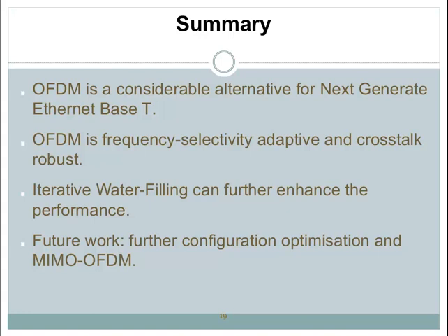And in the future, we will still focus on the possibility of OFDM with better configuration to improve the performance, and maybe also apply more advanced joint signal processing of all 4 lanes together, to apply the multiple-in, multiple-out MIMO OFDM technique, to see what we can do with this cable. Okay, that will be all of my talk today, and thank you.